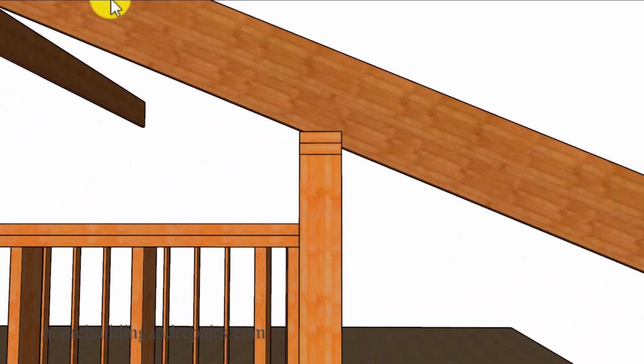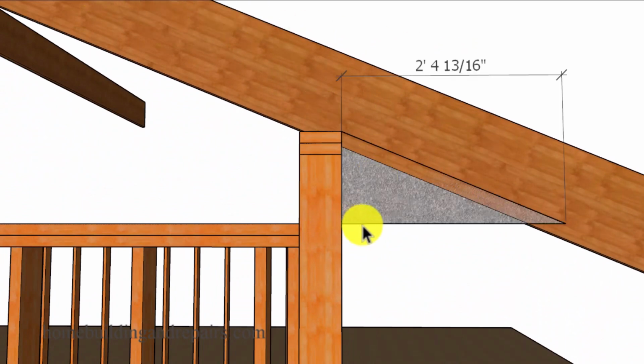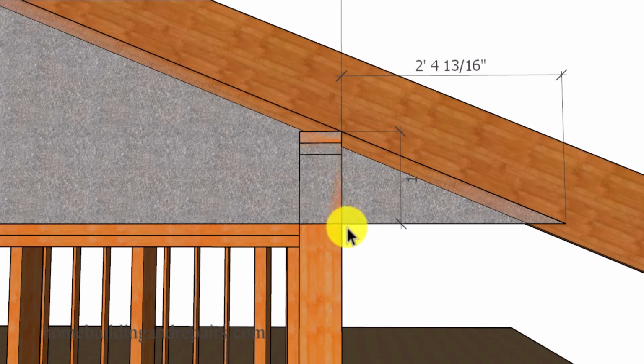So what we're going to need to do first will be to calculate the length here so that we can get the total span of our imaginary building from the difference in the wall framing heights to basically figure out the center of the roof or the roof rafter span on the other side. And then after we figured that out, we can just simply subtract this measurement from the measurement of the span on the other side to get the span over here that we're looking for. So the difference in our wall height is going to be 12 inches or 1 foot.